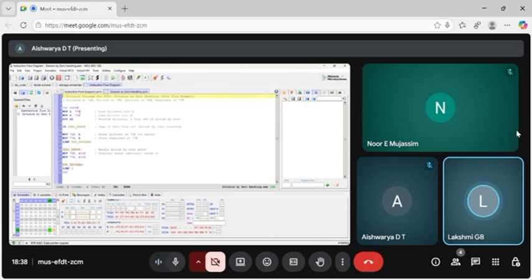Stores results if no error: MOV 76H, A. MOV 77H, B. SJMP end program. Stores the quotient from A to address 76H. Stores the remainder from B to address 77H. Jumps to the end of the program.